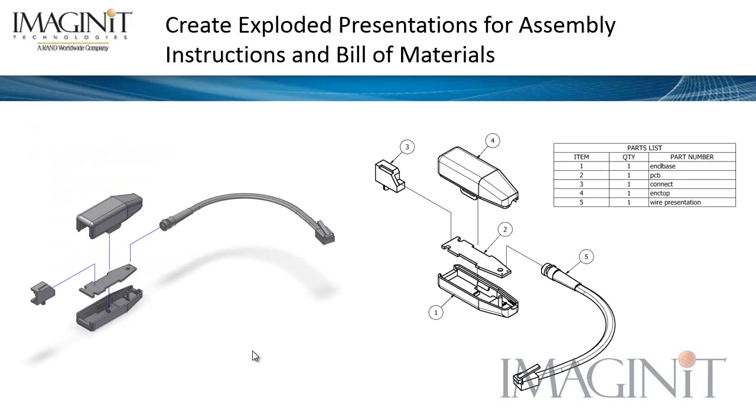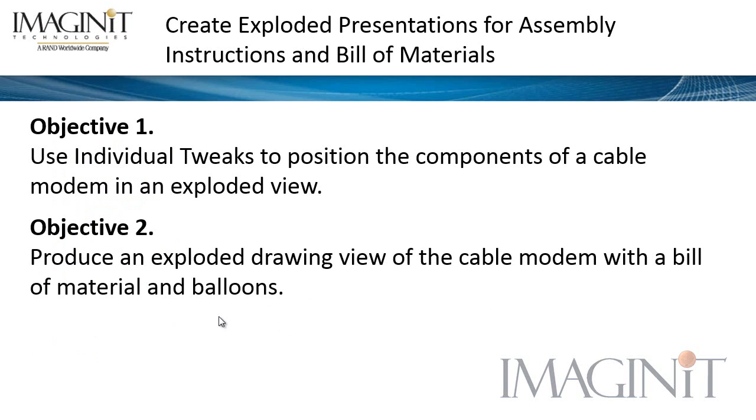Well, in today's presentation, our goal is to create exploded presentations for assembly instructions and bills of material. We really have two major objectives that we're going to achieve during this presentation. We're going to use individual tweaks to position the components of a cable modem into an exploded view. Our second objective is to produce an exploded drawing view of the cable modem with a bill of material and balloons.